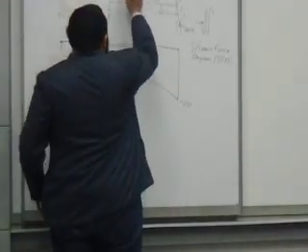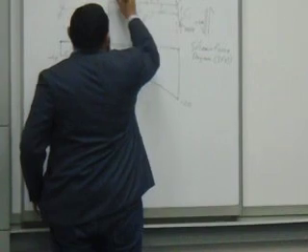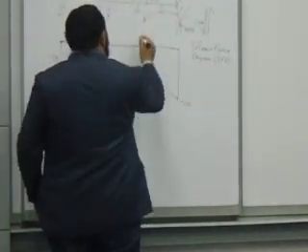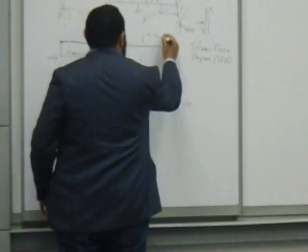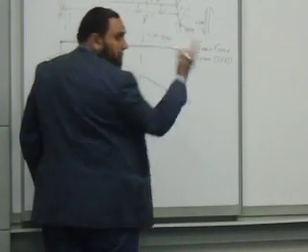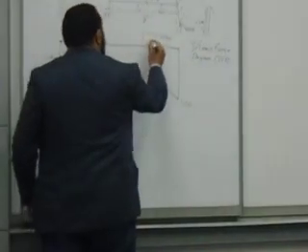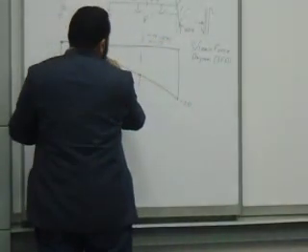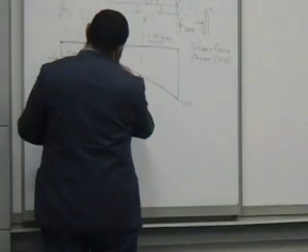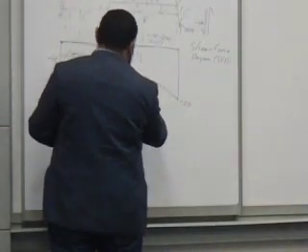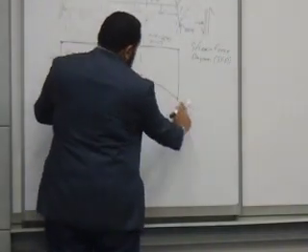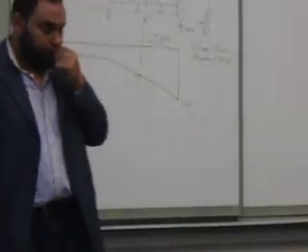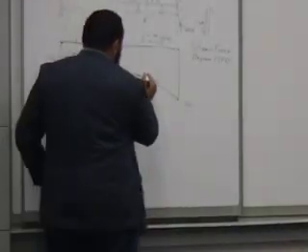So if this distance is 4, and I'm taking a section here and looking, I'm seeing negative 4 minus 2 times 4, not times 8. So this will become negative 12. If you plot here, this is negative 12 and this is negative 4. If you continue, this will be negative 20. It's a linear line. Focus with me on this story.